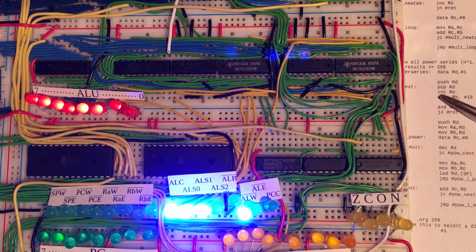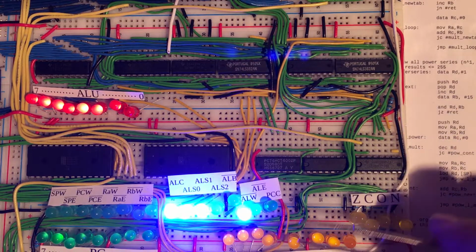And so the work that the ALU will do is very similar to what happened in the last instruction. In this pop instruction, it was in fact the stack pointer which was being increased. And now the value of the D register is going to be increased. So in fact, the D register is on the bus right now, and it's asserting a value of 6, which you can't see right now, but we'll see it soon enough.